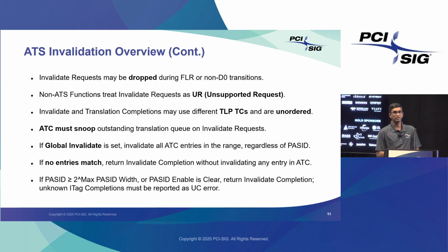If the device does not respond with the completion of the invalidation request, then the IOMMU is in a hold state, not able to allocate memory to other software, right? It may cause an indefinite delay. What happens to the device? There is a timeout mechanism, correct?